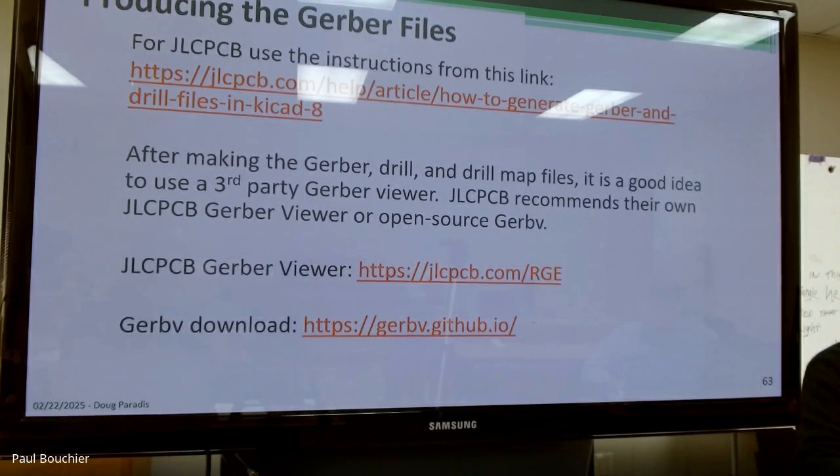What about, have you ever had them assemble anything? I know most of the stuff we do is probably through hole, and they don't like to, you know. If I were working with a lot of ICs directly, not modules, then I would be placing them. Even with this, I did not do a very good job of placing bypass capacitors. And if you're doing bypass capacitors, surface mount ones are so much nicer than through hole. They take a lot less space. But if you're doing it yourself, they're a pain in the butt.